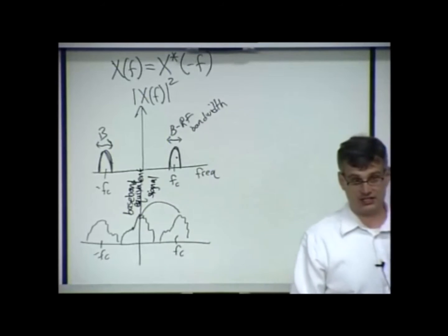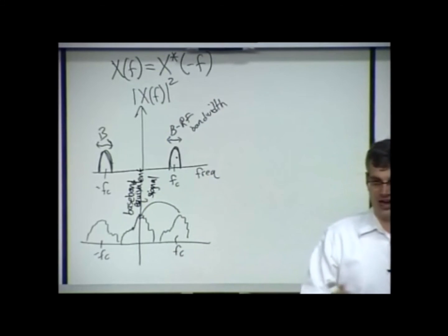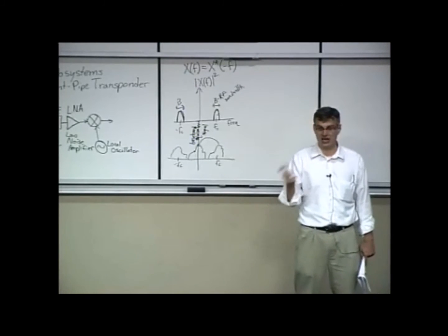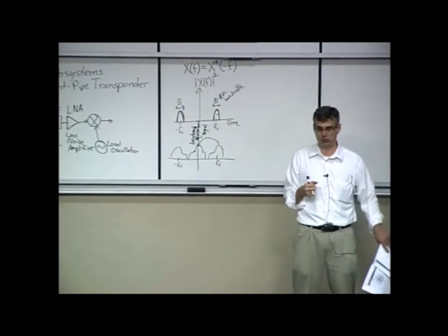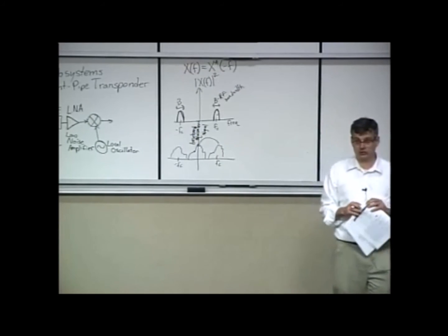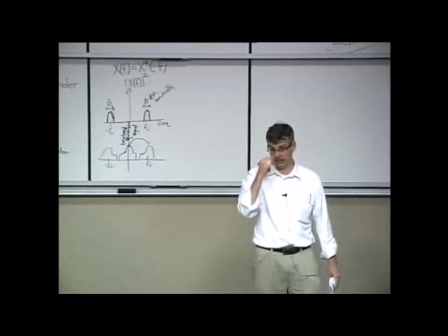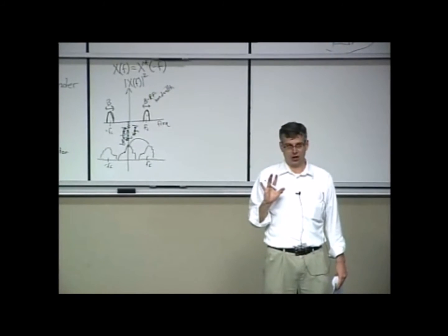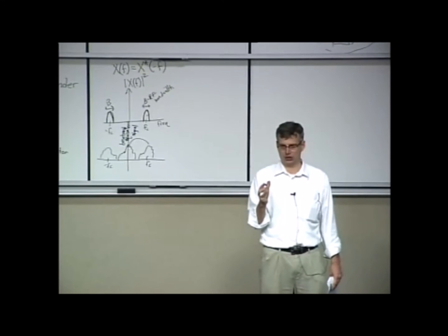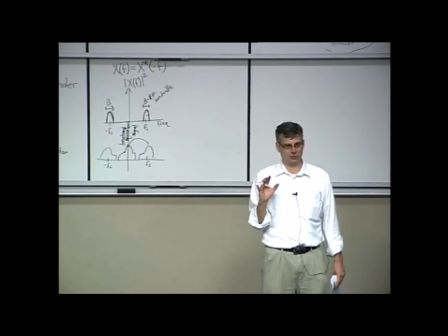And in that case, in order to not have any loss of generality, you have to have a complex time domain waveform. It's not going to be the complex mirror image anymore. So just be aware of that as you look at papers and textbooks from this field and the field of wireless communications in general. If you ever see complex signals in the time domain or spectra that are not the conjugate mirror image, you're usually dealing with a baseband equivalent model.